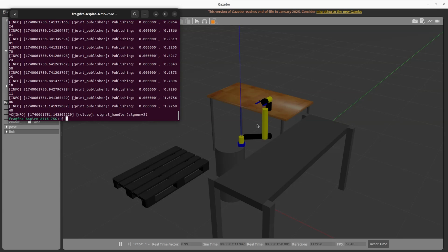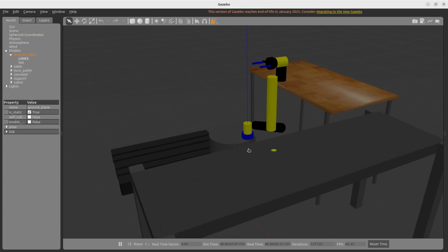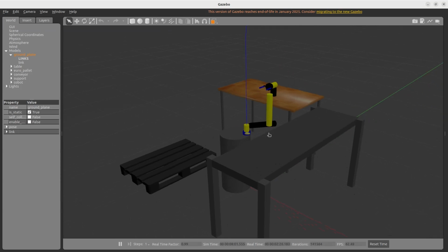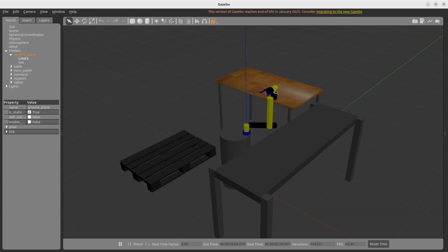But you might know that in a robotic application, the most interesting part is the inverse kinematics, where you're going to set up a certain position with respect to the base link, for example, and then there will be some inverse kinematics algorithm that will find the joint positions to allow the end effector to reach a certain position.